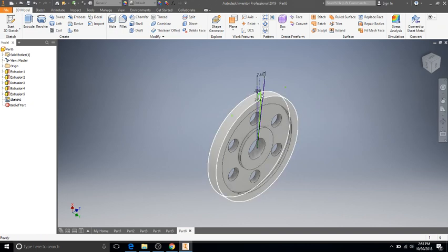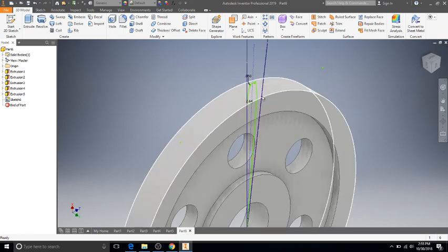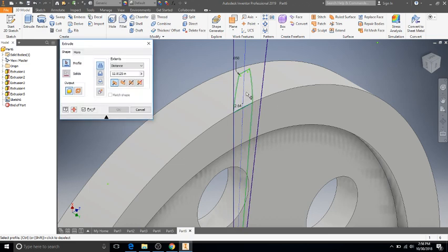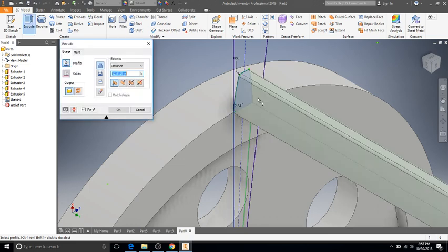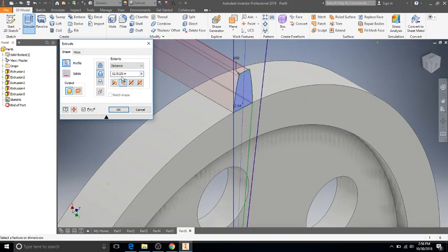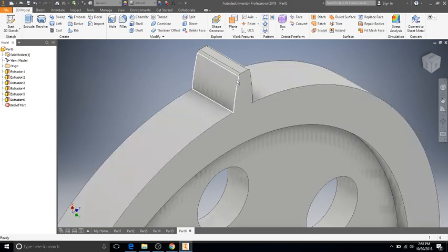Aha! Fantastico. Okay, so now we want to extrude that shape. Just the top piece. Oh dear. And we're going to go the opposite direction. We don't want to cut, we want a regular shape, and we want it to be 1 inch, because that is the thickness. Look at our beautiful gear. That's amazing. Our little tooth. Fantastic.